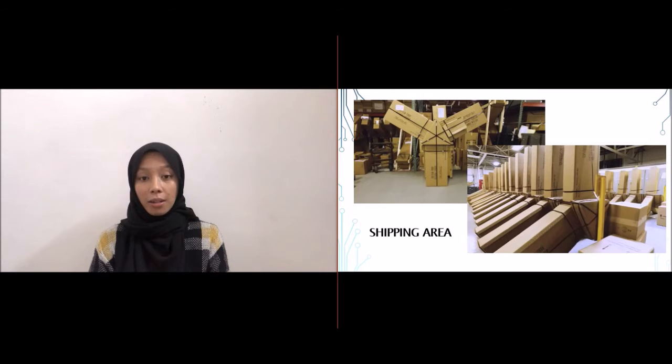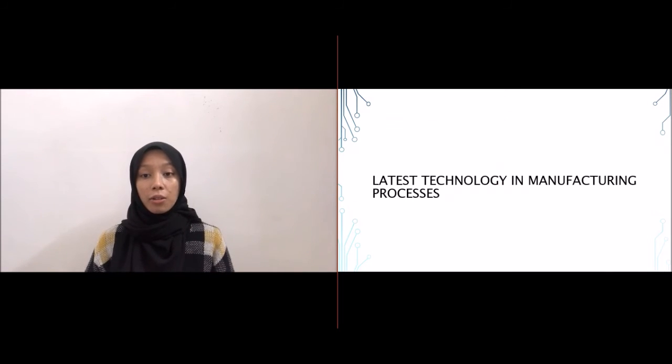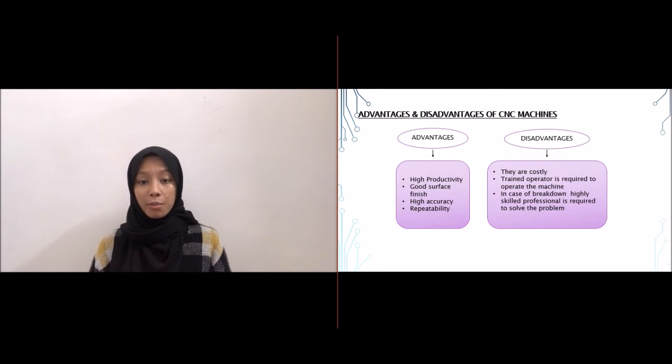Back to you, Anis. Now, I will explain more about the latest technology implemented in propeller manufacturing together with its advantages and disadvantages. The latest technology implemented in propeller manufacturing is CNC machining. CNC machining processes the propeller blade to meet specification by following a coding program instruction without a manual operator's direct control of the machining operation. The complete process of CNC machining depends on computer-aided design (CAD) and computer-aided manufacturing (CAM).